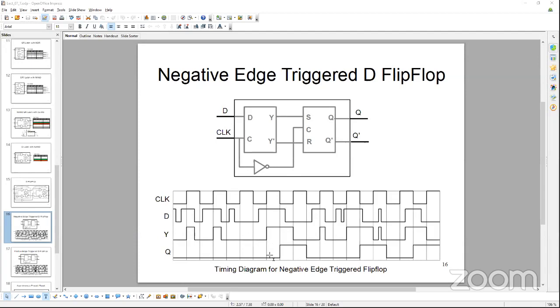If you follow this observation further, you see that during this low logic, Q followed the high, because Y was high, it becomes high, and then it stayed high till the next following logic when Y became low.